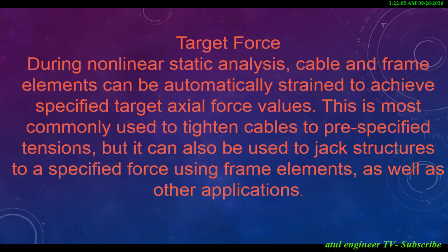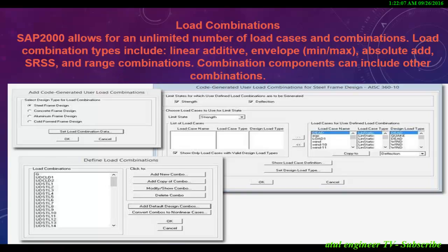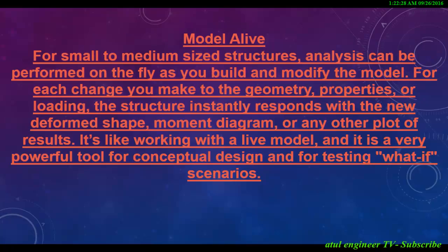This is most commonly used to tighten cables to pre-specified tensions, but it can also be used to jack structures to a specified force using frame elements, as well as other applications. Load combinations. SAP 2000 allows for an unlimited number of load cases and combinations. Load combination types include linear additive, envelope, min/max, absolute add, SRSS, and range combinations. Combination components can include other combinations.